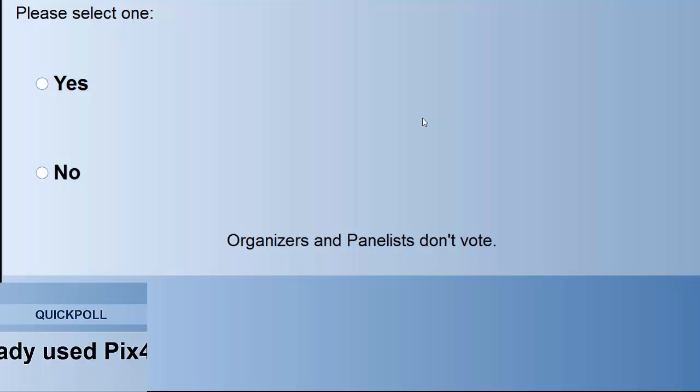The first one is to run a mission thanks to the app and the DJI. The second step is to transfer the images from the DJI to your computer. The third and last step is to run Pix4D Mapper software on your computer, using the images for processing and generating 3D models. All right, that's the big picture.